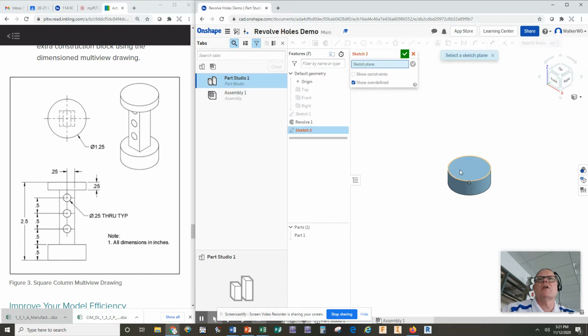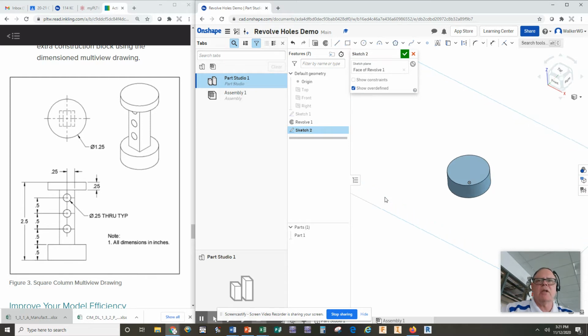So I'm going to add another sketch on top of this one. I'm going to hit N to normalize it. Now this inside square, this dimension is 0.25 halfway, so it's 0.5 wide. And if you do some calculating, 2.5 minus 0.5 is 2, minus 0.25 is 1.75. So this square in here is 0.5 by 0.5. If you look up here, it's a square, 0.5 by 0.5, but then it extrudes 1.75 up, okay?